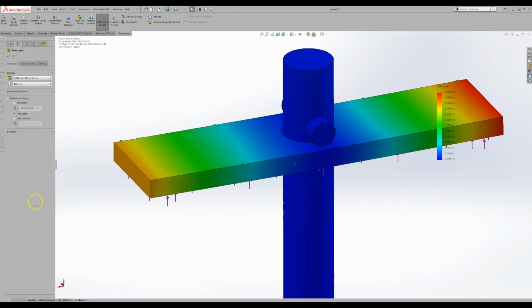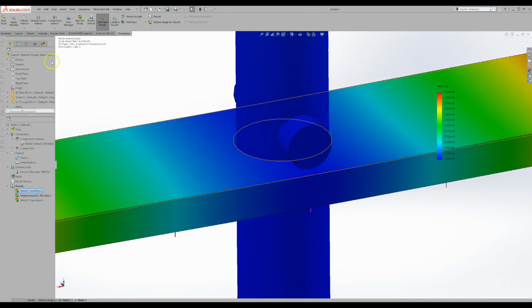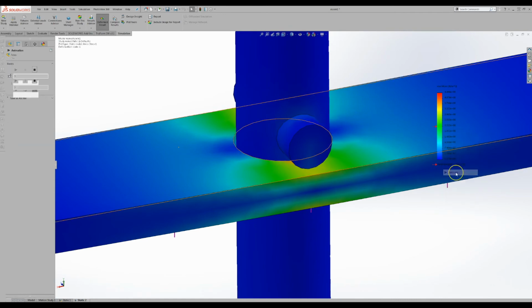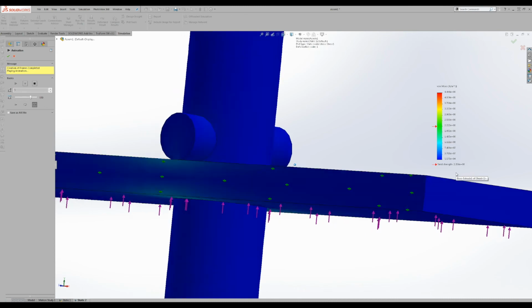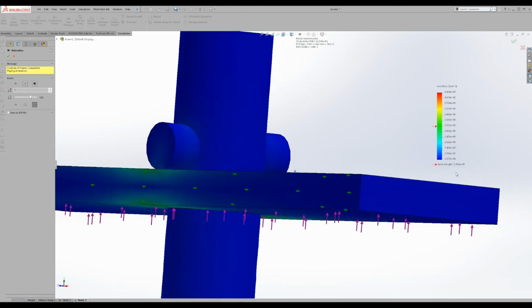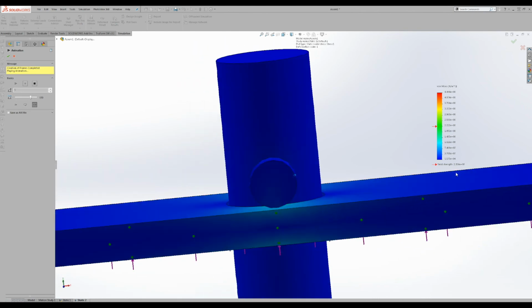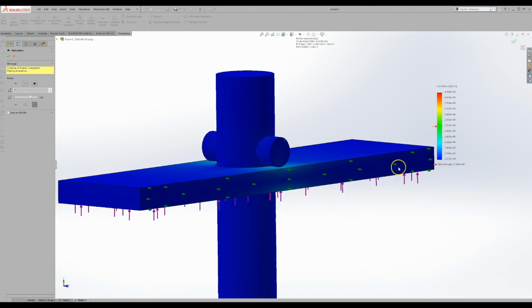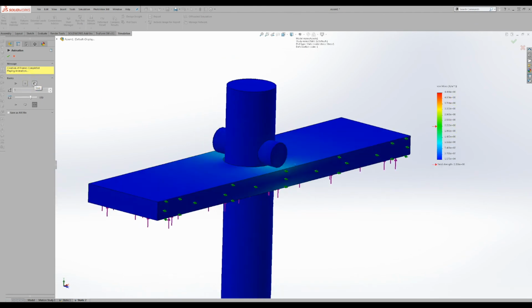Now, you will notice under the von Mises stress that you'll see in a second, you get some ridiculous values, and that is simply just a stress singularity, which again is a rudimentary FEA concept, and perhaps I'll do it in a different video. Do let me know if you want to see some more FEA topics like this. So the model is behaving as planned. We've got a force pushing up from below, we're inducing a stress in the pin, we're getting a bending force or moment in the bar, and displacement looks sensible.